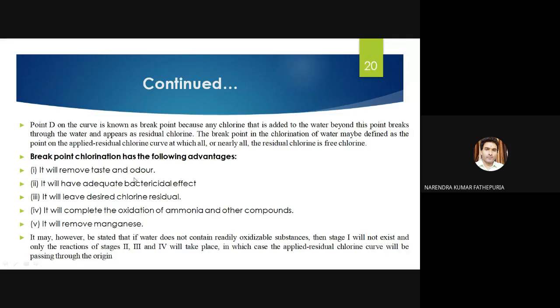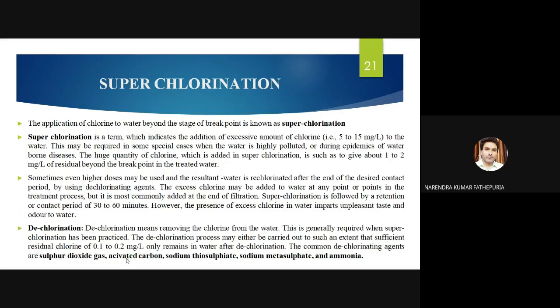So these are the following advantages. It will remove the taste and odor. It will have adequate bacterial effect. It will leave desired chlorine residuals. It will complete the oxidation of ammonia and other compounds. It will remove manganese also. Then we have a superchlorination.